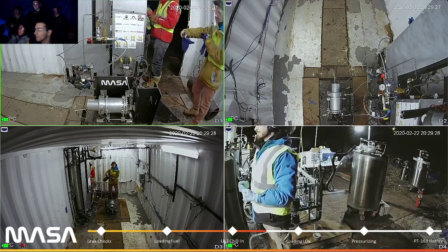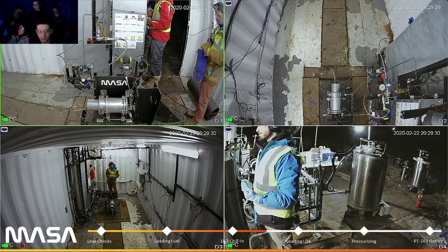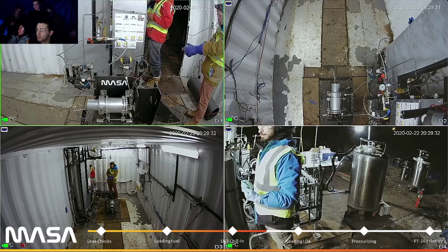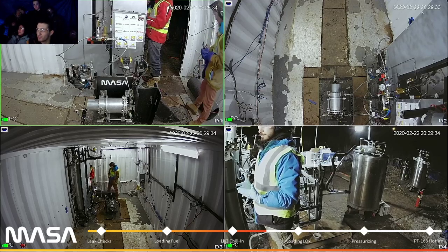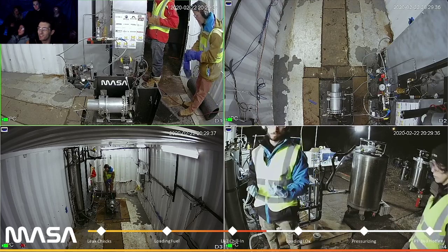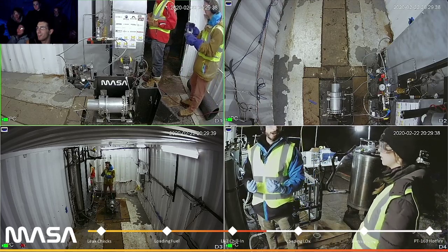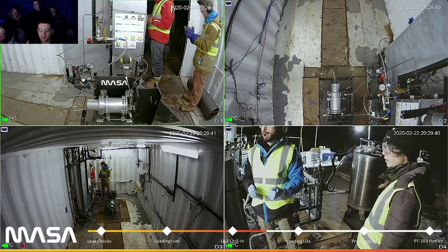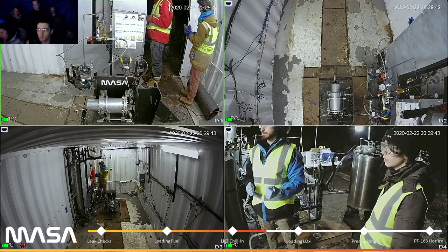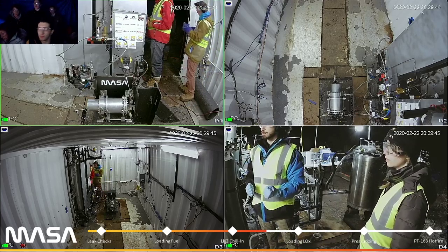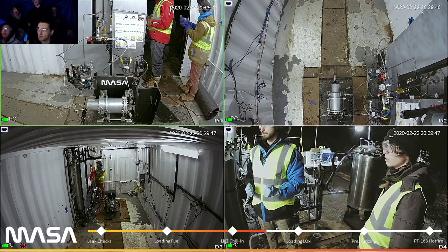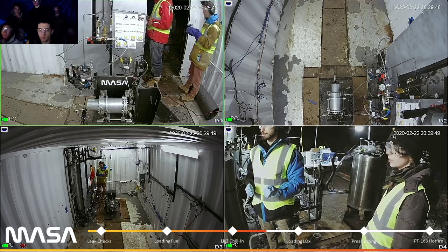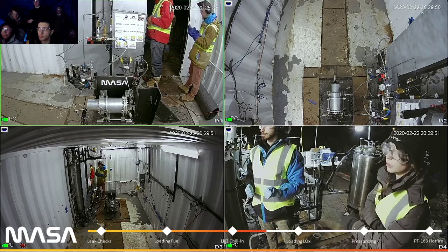We're now going to progress into my always favorite part of Hotfire, which is watching John and Jeff use progressively larger wrenches in order to work on that tank on the bottom of the box. Right now we're chilling in LN2, and generally when this happens, the big fitting at the bottom of the tank for the main propellant line will drip a tiny bit when it gets cold, so we'll come in and tighten that a little bit more, and then continue on.